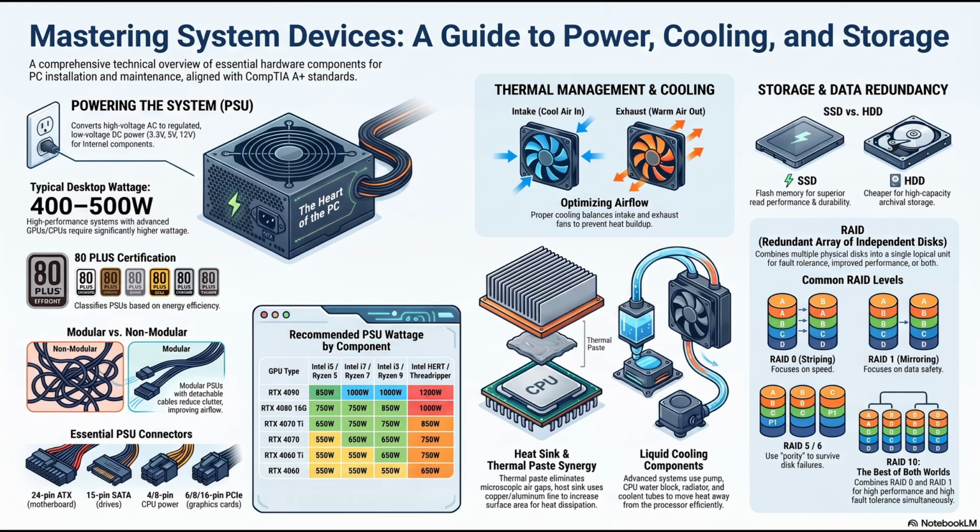So if a system isn't turning on, a technician can take a voltage meter, stick the probes into the yellow and black pins of the ATX connector, and if it reads 10 volts instead of 12, they instantly know the power supply is failing to deliver muscle power. It isolates the variable immediately. You don't have to guess if the motherboard is dead or the PSU is dying. The wire colors tell you exactly what to test.